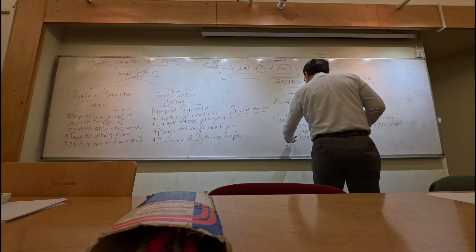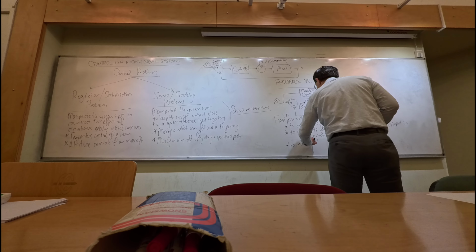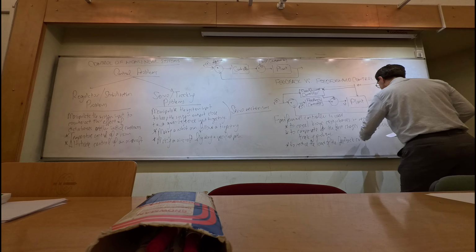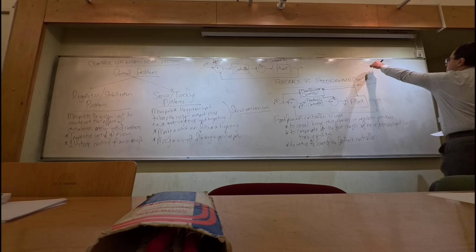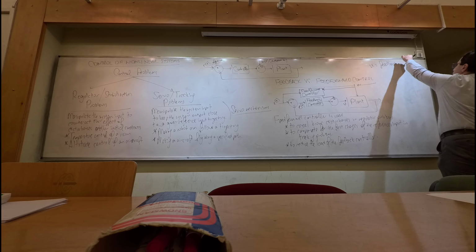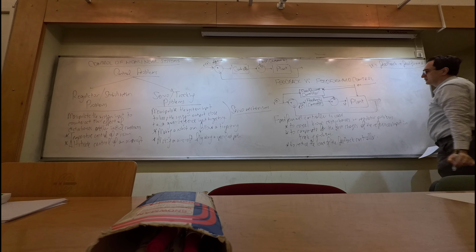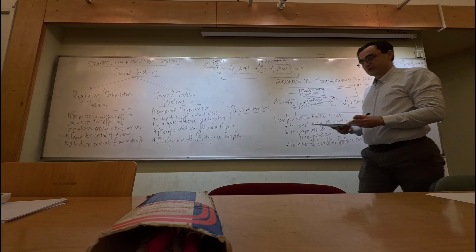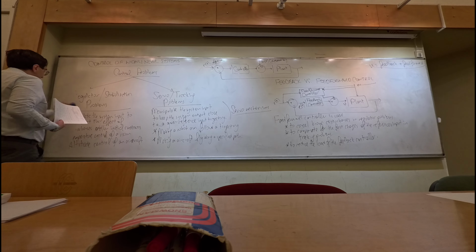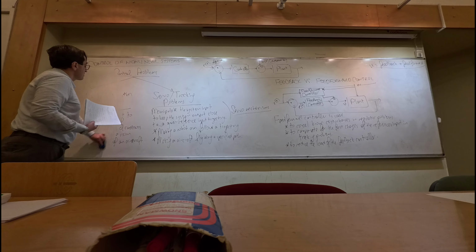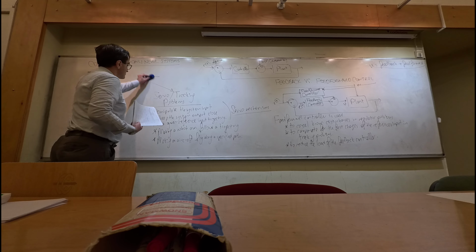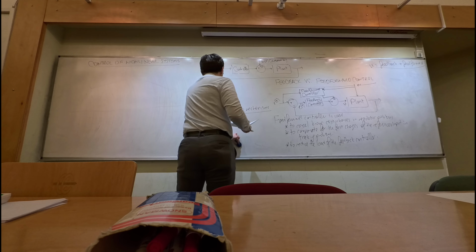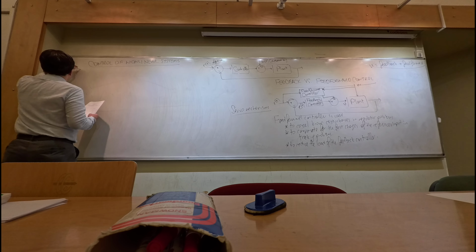And overall, it is used to reduce the load of the feedback controller. In general, the input that we are selecting is the summation of the feedback controller input and the feed-forward controller input. So in some way, when this feed-forward controller takes some action, it reduces the load of the feedback controller. Here let us look at an example. In this example, I will consider the temperature control of the room.